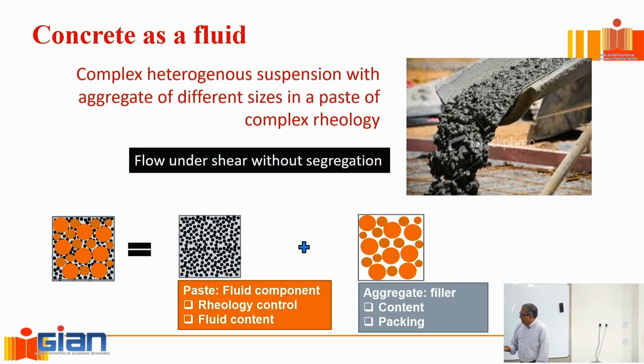Therefore, if I look at this as my concrete, I can separate out the paste and the aggregate. I can separate out two phases in there, right? The so-called fluid phase, which has a rheological behavior, and that is my fluid component. Then I have the solid component, which is the aggregate, which basically serves as the filler, filling the space in there. And each component has a role to play, as we'll explore.